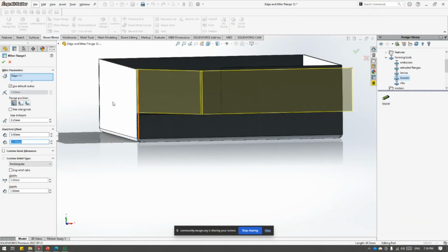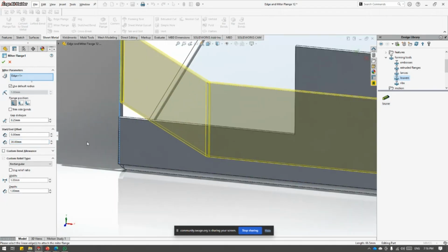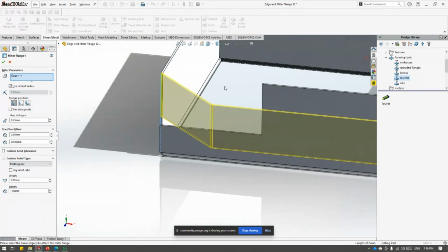If I increase this value, like maybe I make it 30, you are expecting that this extrusion will increase downwards. I am putting 30, clicking enter, it's going back. So which means this D2 is not the extrusion length. It is actually the length from the face, and that face is this one, the base flange that we already have.